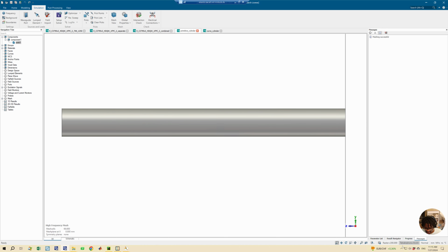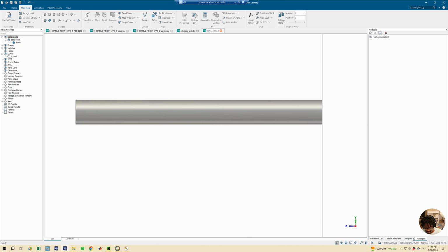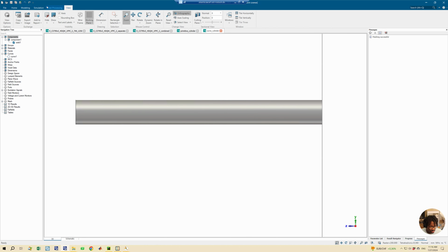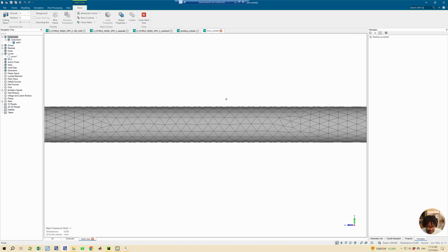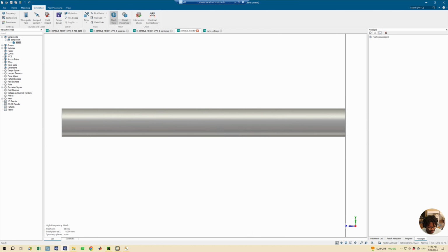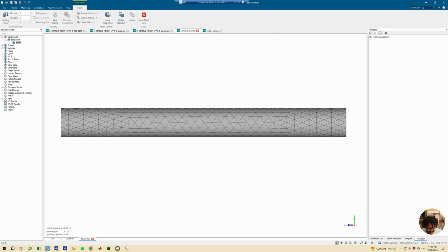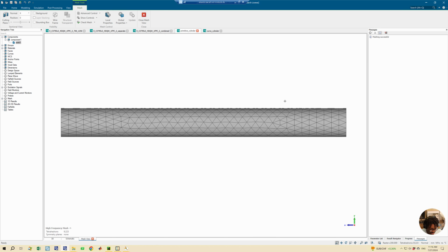So you look at the number of tetrahedrons, you have 9,203. Then you look at the number of tetrahedrons here, you have 9,360. So about maybe 140 or 137 tetrahedrons more. And then looking at the mesh, if we look at the mesh view to see if there's any significant difference, I don't know if you'll be able to tell using the eye. Yeah, you might not really be able to tell visually, because if you look at the patterns, it looks exactly the same for both models.